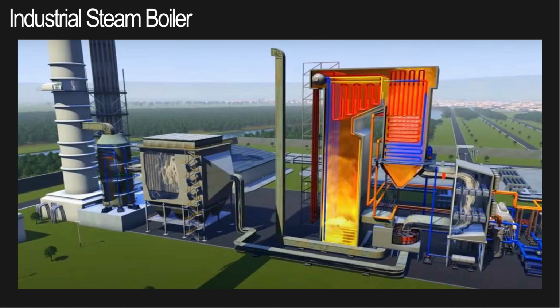So pretty much why the radiation zone is exposed to the steam drum is because the majority of energy required to vaporize the water is the latent heat. That's why you have the magnitude of energy coming from radiation meeting the saturation. Then beyond that, it's sensible heat, and you can use the residual heat of the flue gases downstream of the radiation zone to further superheat the steam before it goes to the steam header.